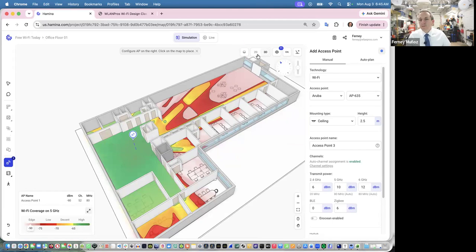It's just sending waves and predicting the attenuation. The scale then, once you give it the scale, gives the software a more accurate prediction and a more accurate distance for it to do math. This is doing RF math for you. This AP with this radiation pattern at these power levels, at this height from the ground, is sending waves: double the distance, quarter the power, double the distance, quarter the power. And then it shows you down here using a color.